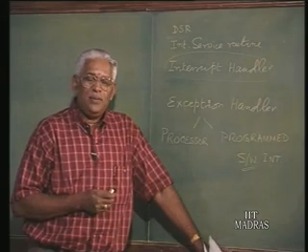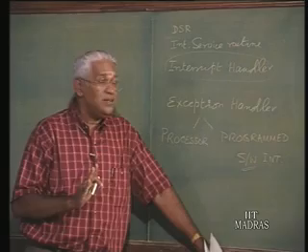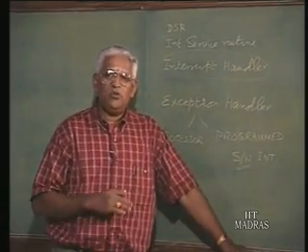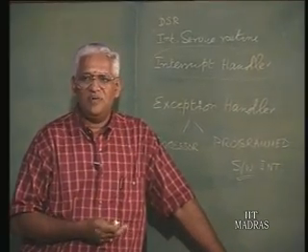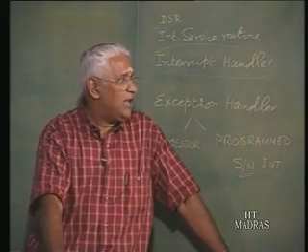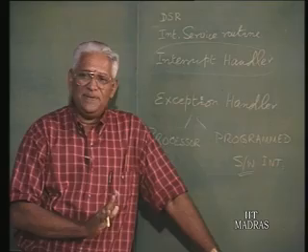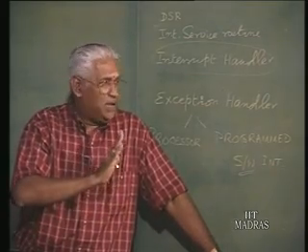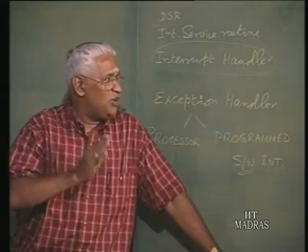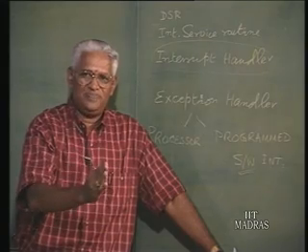Now, we say power failure causes the CPU to be trapped, meaning the AC power is dipping and DC power will go off in another few milliseconds maybe, and before that a few instructions will be executed, possibly for trap handling, meaning bring it to a logical portion, that is, the end of the current instruction, and stop.